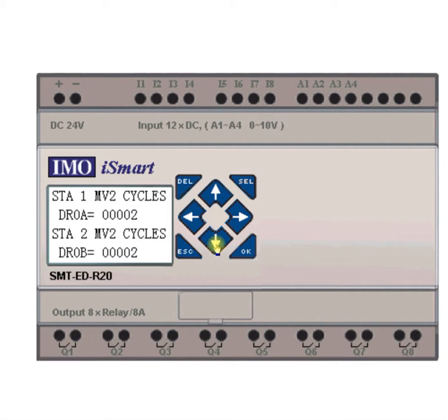And this is where you can adjust the number of cycles per load, which normally you would set at 1 or 2. You can set it higher than that, but you can't really keep control over your percentages if you do that. So if you set it at 2 cycles, it's going to load virgin, regrind, virgin, regrind, as opposed to 1 where it will just load virgin and then regrind. So this is how many times the valves cycle during the loading process, but it still remains that portion of 10 seconds and 4 seconds, which is adjusted separately for each station.